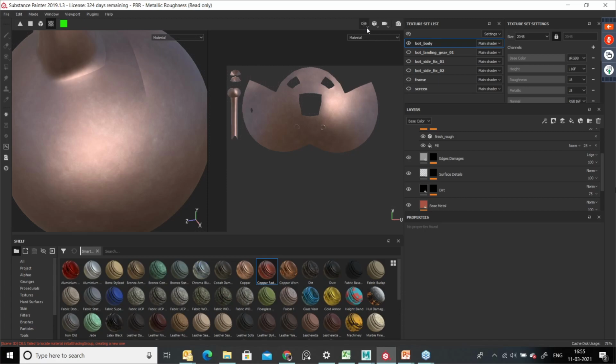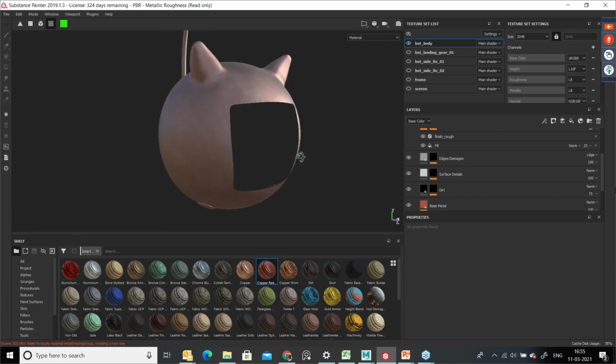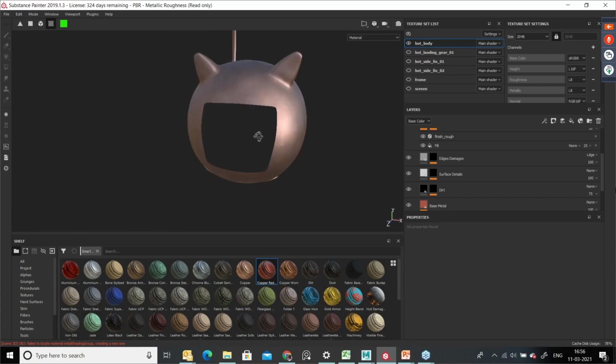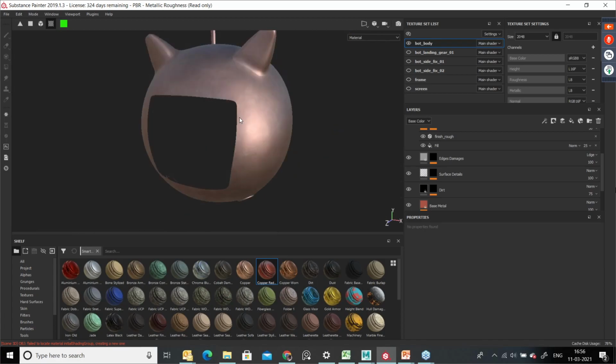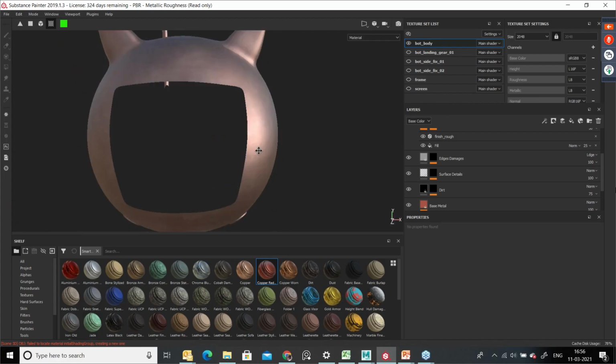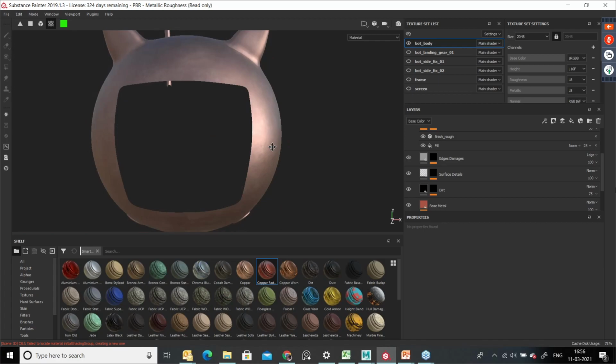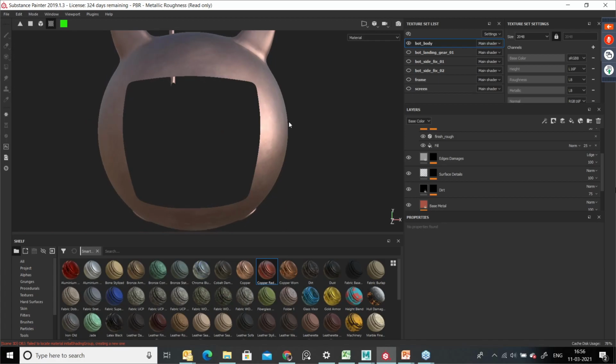And some questions I saw, like backface culling. Backface culling, in the sense that the inner portion looks transparent. How can we avoid that? See, this transparency is because the normal direction is reversed. The outer surface has a proper normal, the inner surface doesn't have a normal, because the normal is outside only. Because of that, it looks like this.